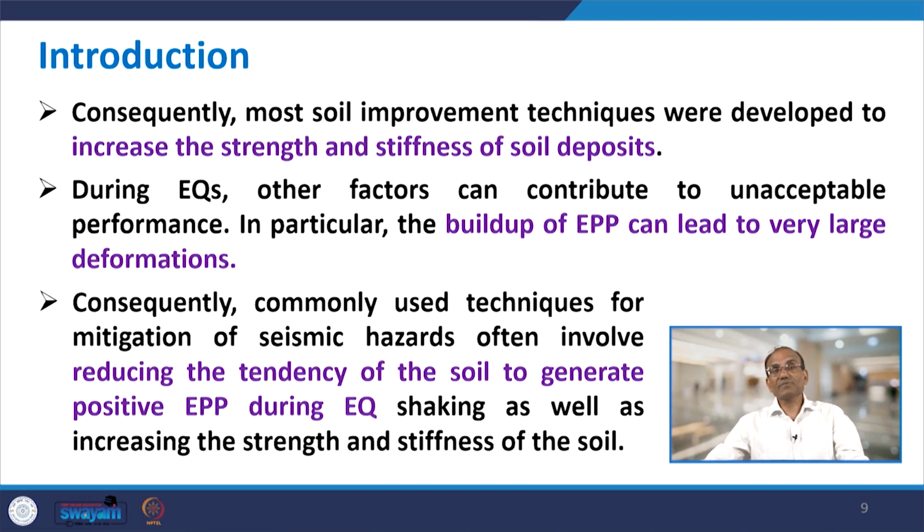During an earthquake, other factors can also contribute to unacceptable performance. In particular, the buildup of excess pore pressure can lead to very large deformations. So, when you consider earthquake forces, in addition to the issues in the static case, there is development of excess pore pressure, particularly when your soil is saturated, and that needs to be considered.